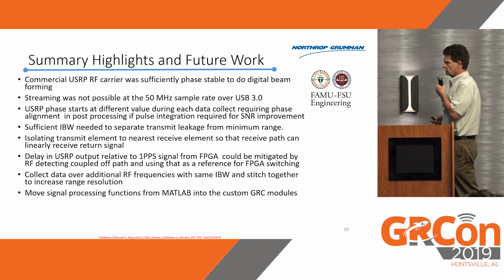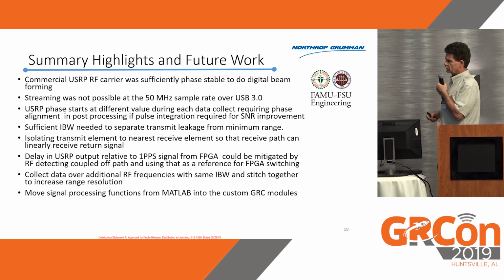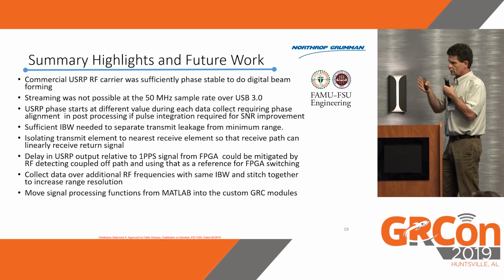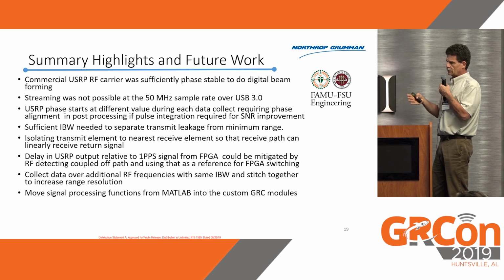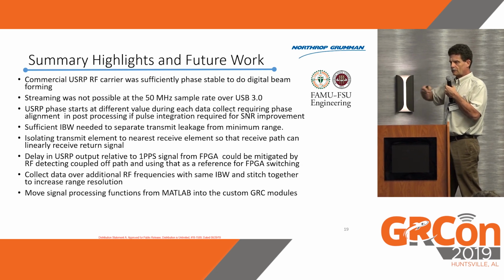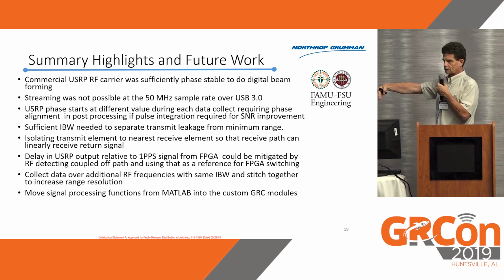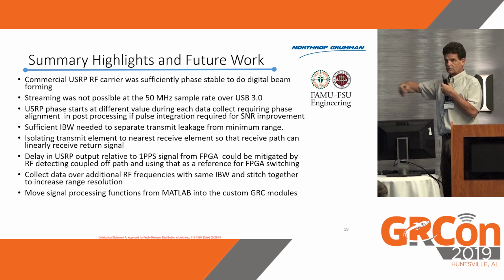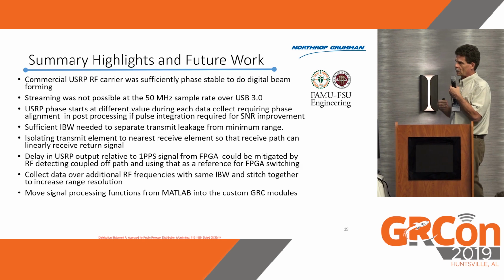And then the other thing we discovered is that with the 1 PPS that launches the waveform out of the radio, well, that's great, but there's a delay. When you tell the radio to give you a waveform, there's a delay from when that waveform actually comes out the spigot of the radio. So there was an extra delay. We had to empirically determine what it was.